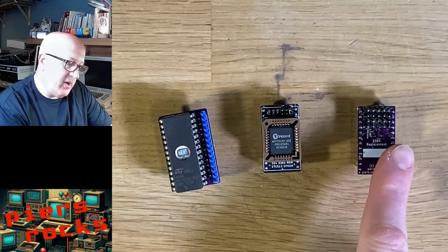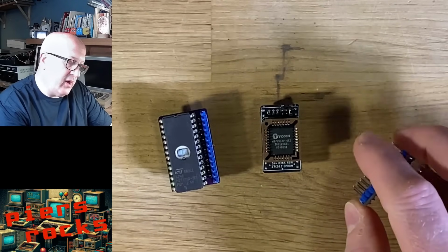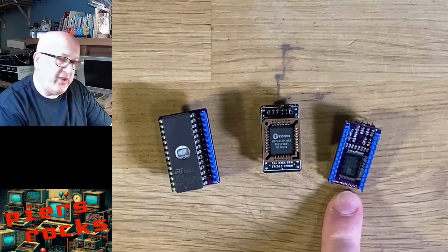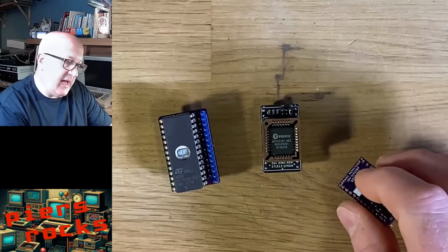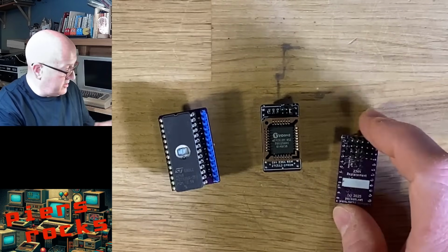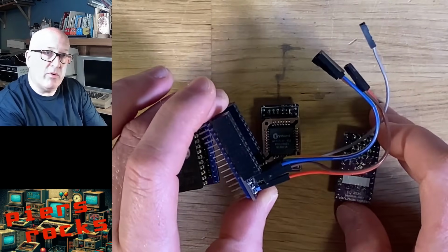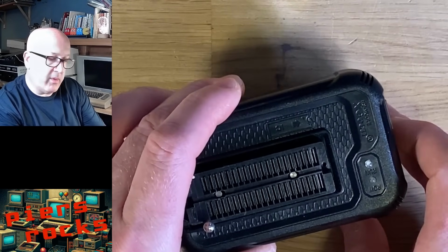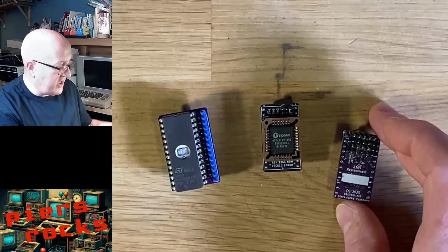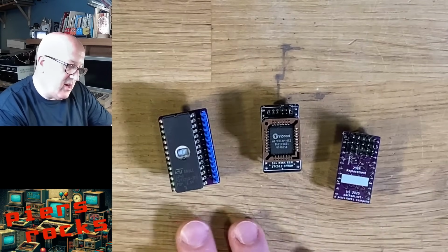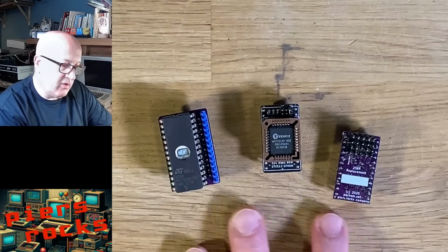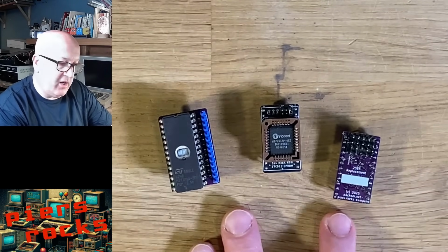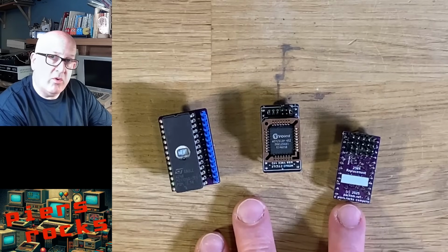And then this third type I came up with, and it uses a brand new flash chip from ST on the underside. But again, this needs to be removed from the host, inserted in a programming jig, the programming jig put in EEPROM programmer and reprogrammed. So this can still take you a couple of minutes. And every remove, reinsert cycle risks damage to either one of these components or your host system.